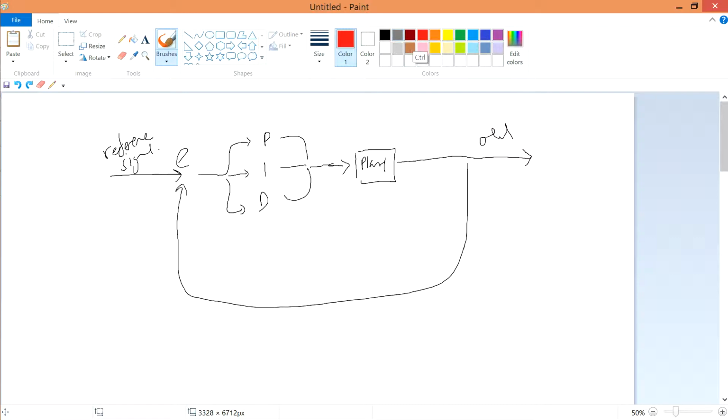So how does this do things with that? The proportional controller is simply multiplied by a gain. It's just proportional, meaning if the error is 5 and you expect your output to be 1, you just multiply by 0.1. So 5 times 0.1 is 1. This is the method to use the proportional controller to this extent, so you need not activate I and D. But things are not that easy, as we will see. Let's continue first. Actually this should be Kp.